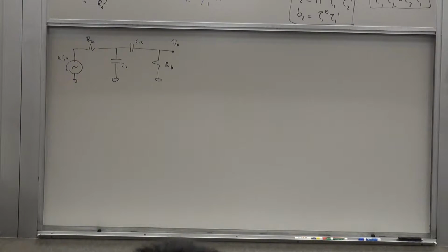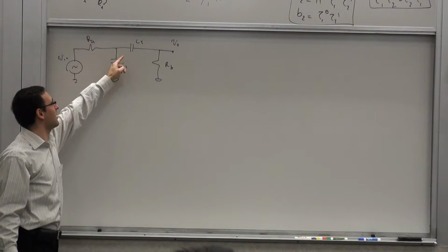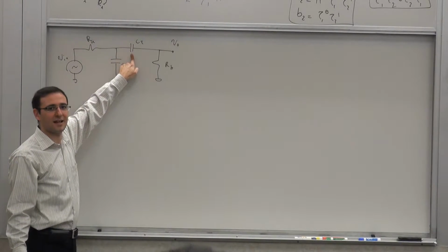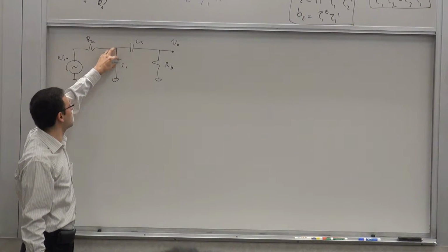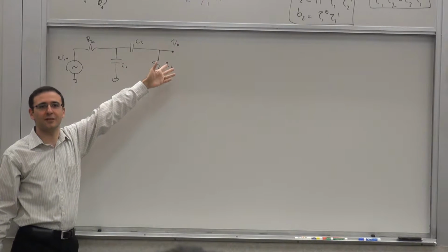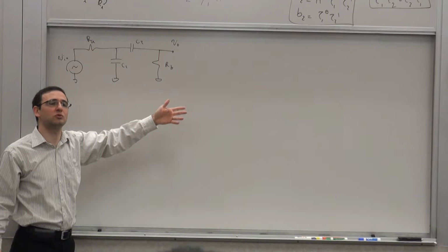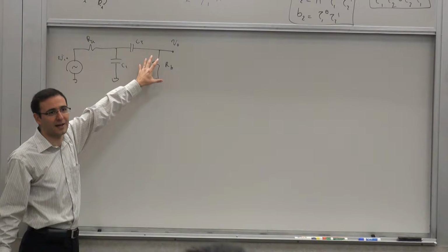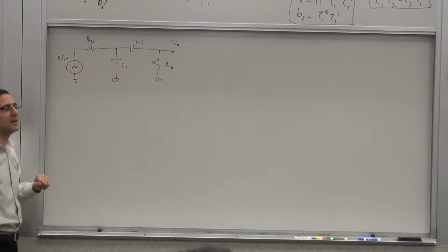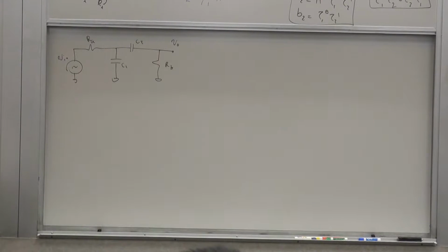Well, there are different ways to think about it. We can evaluate the behavior of the circuit in frequency. Yeah, but without evaluating. Just setting zero frequency, both capacitors are open, so there's no output. So at DC, nothing goes through because of this guy. At infinity, this is shorted, so nothing gets to the output. So at 0 and infinity, your transfer function is zero. Your way of thinking about it is also valid. You say it's a low pass followed by a high pass. That's also valid. There are different ways to think about it.